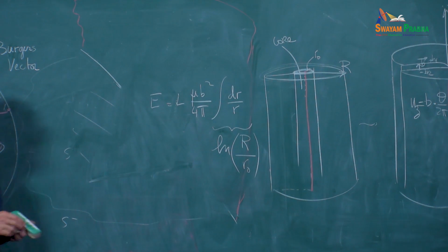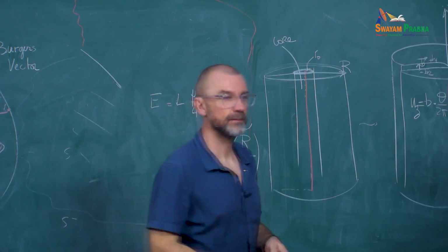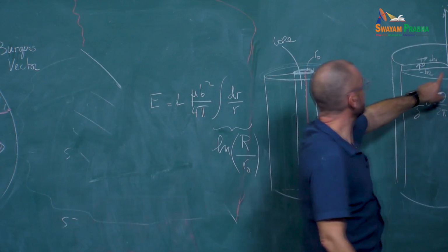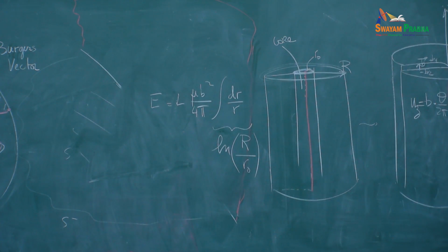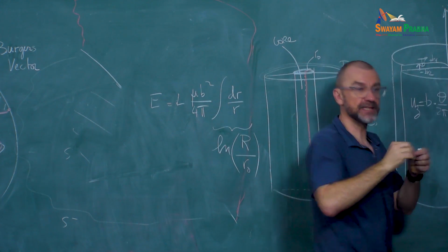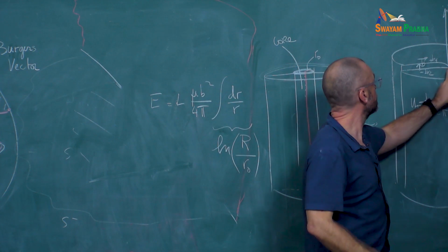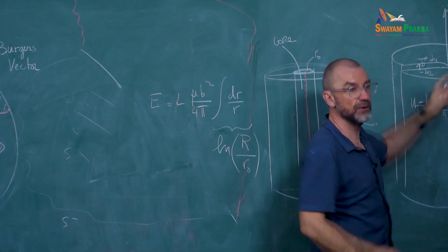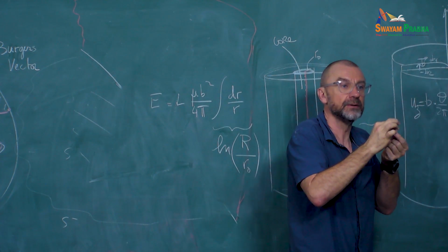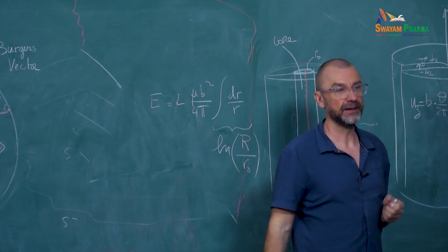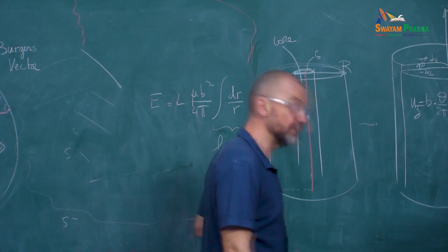So what was basically the source of that blowing up at zero? It's because, if you look at the displacements, they do not depend on r. So when you are very close and you are turning around, your displacement gradients are infinite, because you are still going from minus b over 2 to b over 2 over a very small perimeter. And so your gradients explode, and that gives you the singularity.